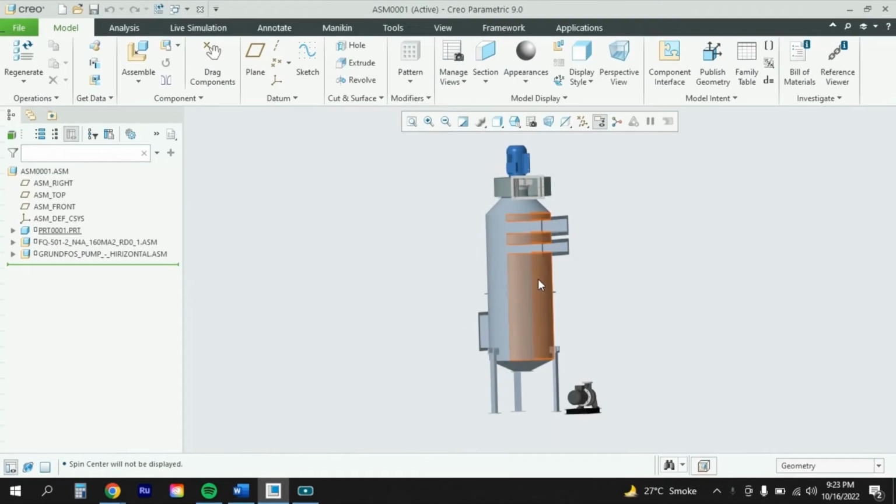So once the scrubber is created, I have added one low pressure fan above it, and the flange is matching with the flange of the low pressure fan, and I have added this additional water pump here. So that's how the assembly of a wet scrubber will be completed. So this is the inlet of the dirt air. This will be connected through piping, and there will be a hood from where you will be getting your fumes. All the fumes will be collected into that hopper, and from the pipe it will go and insert here.